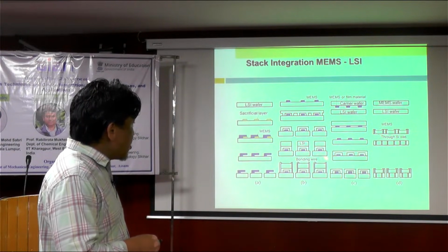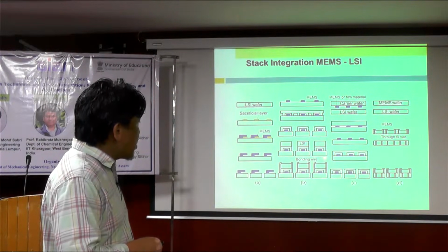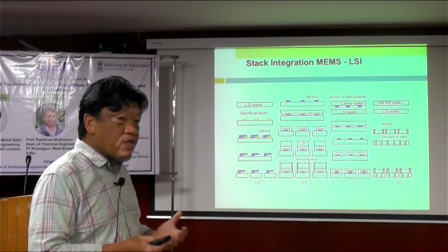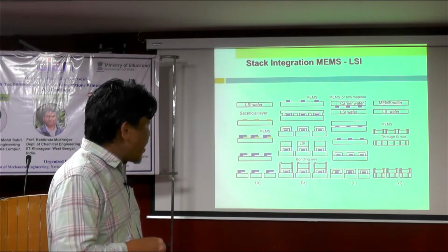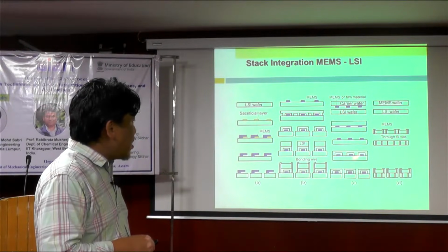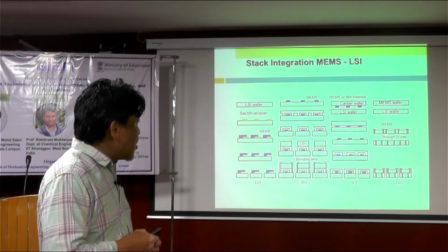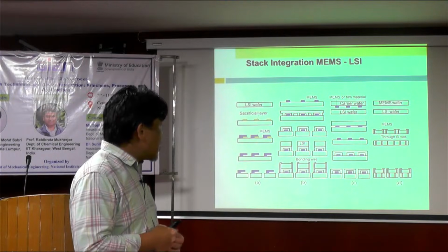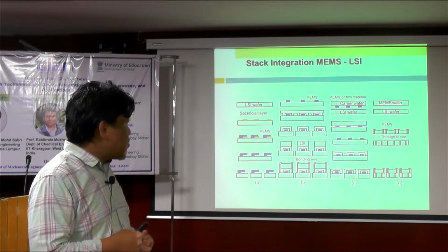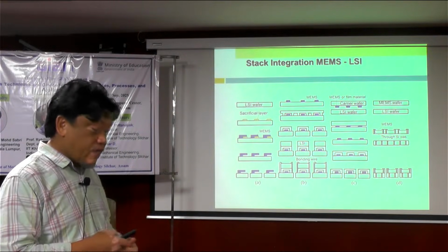In other cases, there is also wire bonding. Sometimes we have to have both because of the complexity. But if we can have a through silicon via, then it might reduce a lot of hassle in connecting the electrical components together, and also reduce the power consumption and improve the efficiency of the device.